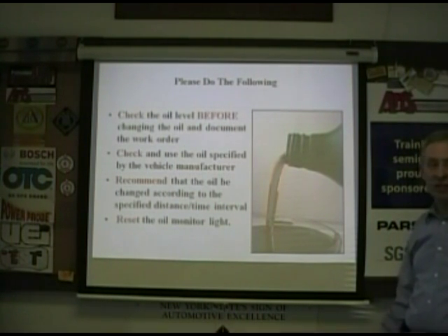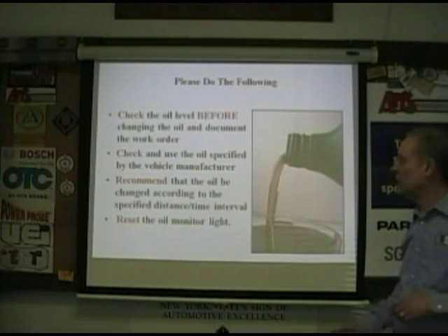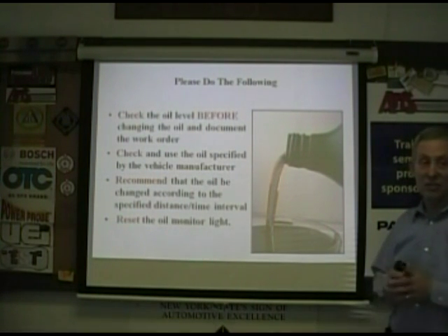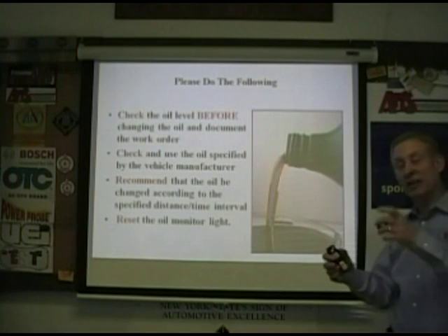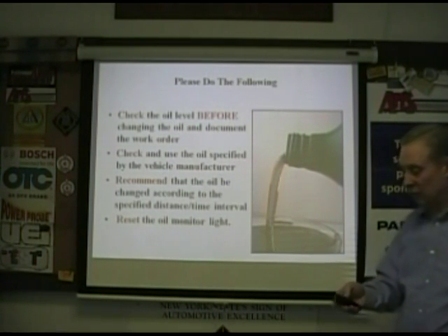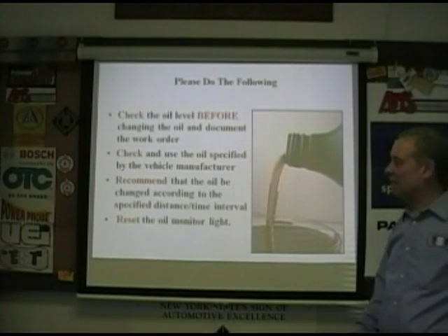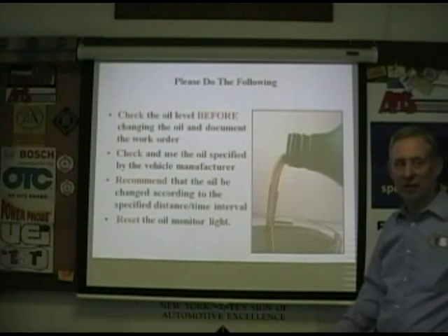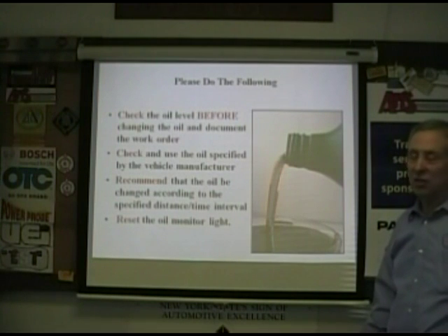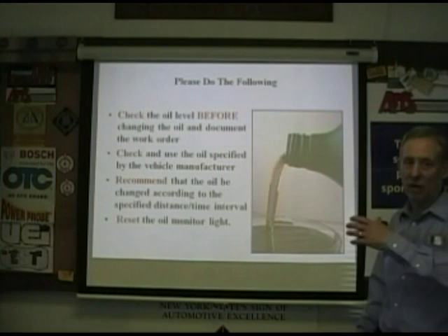There are test facilities. They generally send you empty containers and a return envelope, and you take a sample of the oil. My recommendation on that is warm it up, let some drain, get it from the middle of the stream, and then send it off, and they'll give you a result. However, with testing oils, one test is not generally all that. If you're really concerned about the life of your engine, unless it's a catastrophic failure, generally you have to test a sequence to get an idea of a wear pattern.